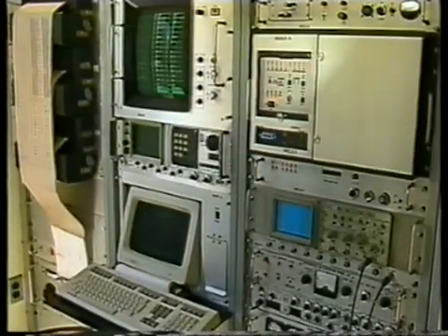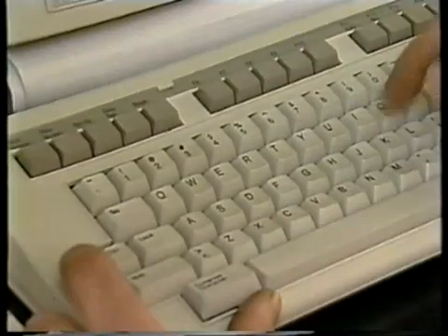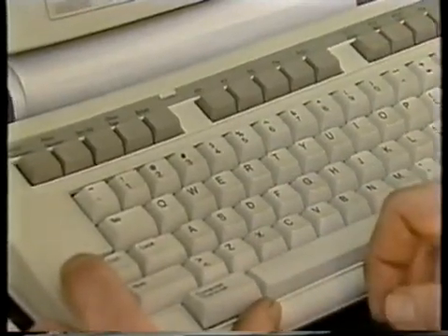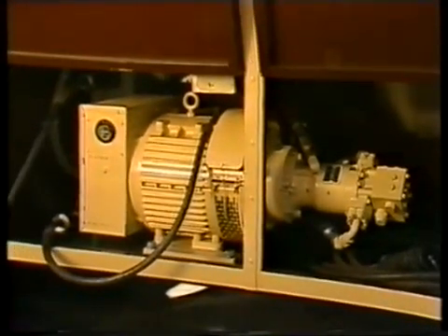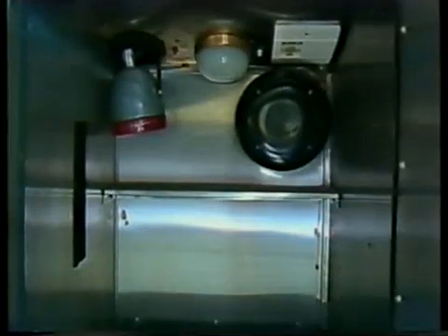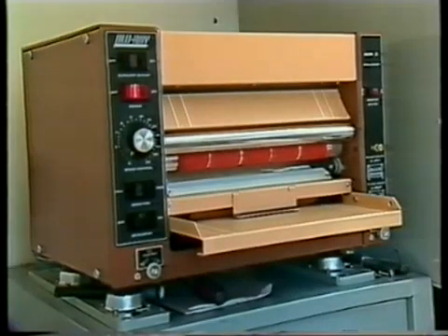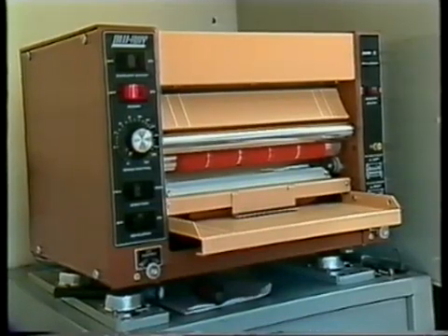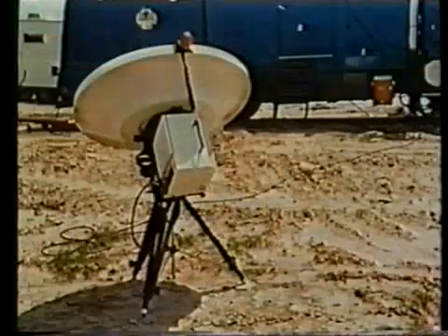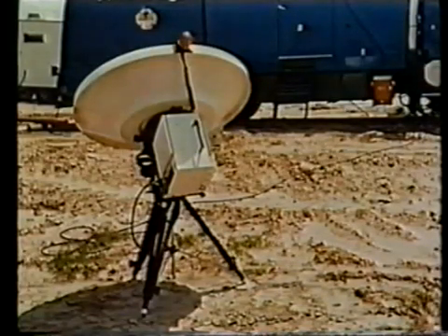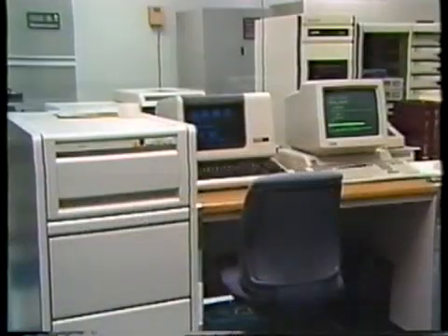The computer is vital for receiving, viewing, and adjusting downhole tool responses, for storing and manipulating data, and for recording field logs. And finally, support capabilities, such as a generator to supply electrical power to the unit, a darkroom to develop log film, and reproduction facilities for making field copies of logs are considered standard equipment. In some units, satellite communication equipment is available that transmits log data directly to oil company offices, or, if required, to regional processing centers for further interpretation.